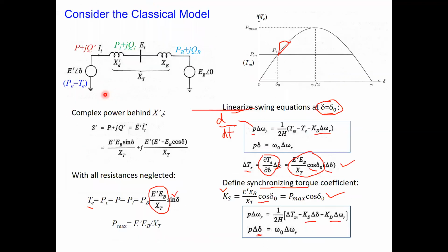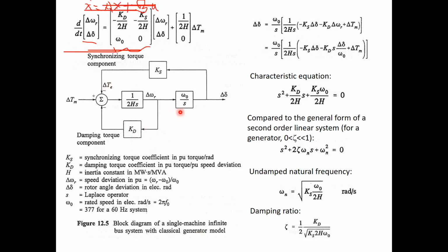If you refer to the previous, del Te is minus here. But what is Te? It is Ks times del delta. But del delta is the state variable here, so it will be the feedback. So this is your feedback: Ks times del delta, that is your del Te. So you draw this line. This is the signal path here.